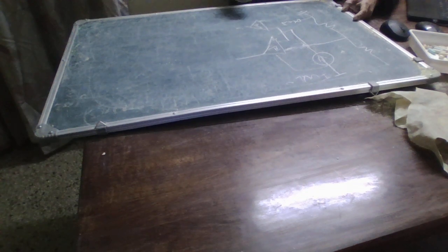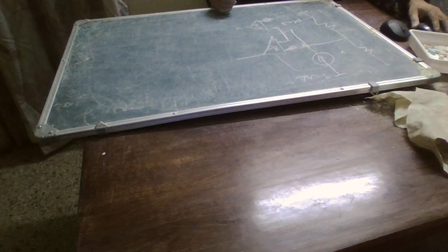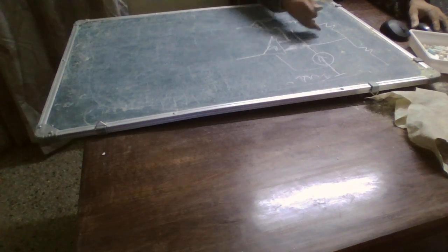Sorry, I made a mistake in drawing here. If the time duration is greater than 1.5 microseconds and the bias voltage is greater than 2.7 volts, the device starts up and the internal configuration starts. This is the startup of this IC.